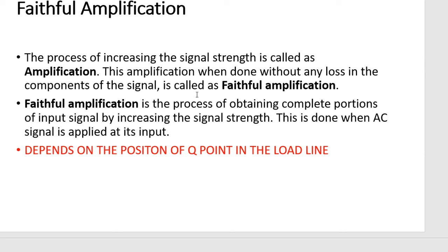For faithful amplification of the signal, the Q point has to be properly selected. While we design a transistor circuit, the Q point should be selected in such a way that it amplifies the signal faithfully, that is, the signal is not distorted. There is no distortion in the output waveform.